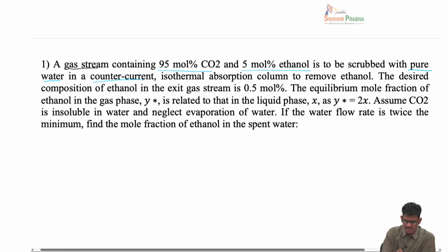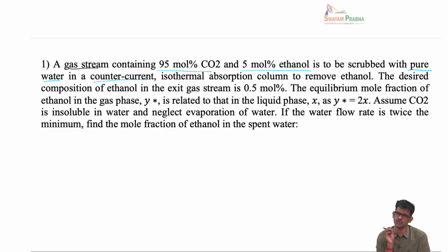Generally in other problems we assume CO2 is actually soluble in water or aqueous ammonia solution and so on. But in this problem the solute is ethanol and the liquid is water, and we are assuming only ethanol is transferring from gas phase to liquid phase. And here the counter current is explicitly mentioned. If it is not explicitly mentioned which operation it is, you are going to use counter current. If it is co-current, it will be mentioned.